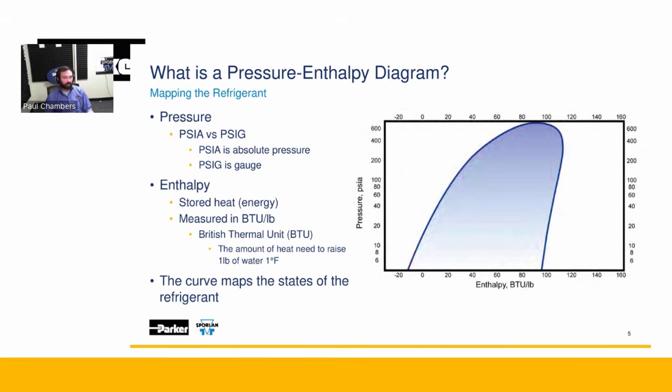You've filled up the air in your tire before. You've probably been around something that's pressurized. If you see an A on it, all it means is absolute. So earlier I talked about where these boil at sea level. Well, absolute means right here where I'm sitting in Washington, Missouri, we have 14.7-ish PSI just in the air around us. That's all the air above me pushing down on me right now, creating about 14.7 PSI of air, and we don't even notice it. It doesn't register. If I had a gauge in my hand, it would read out 0 PSI.